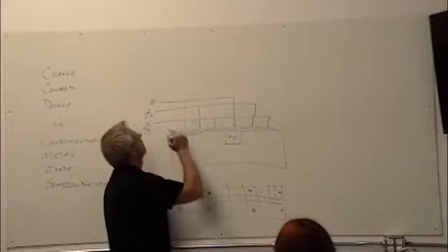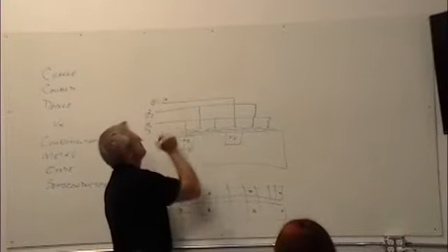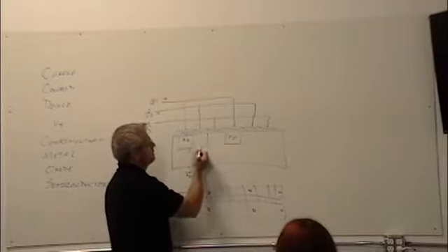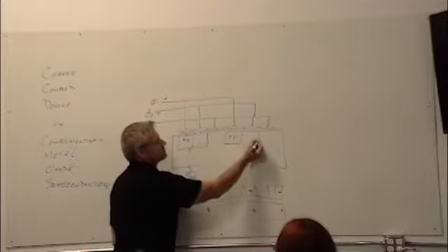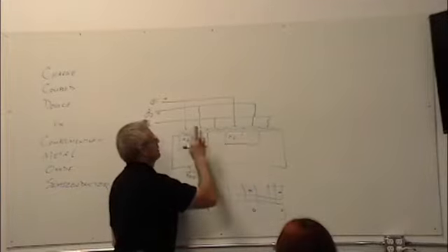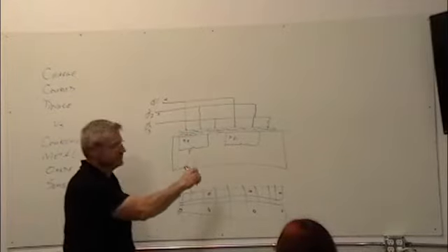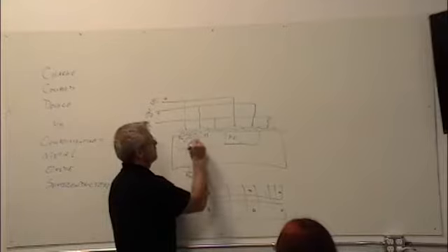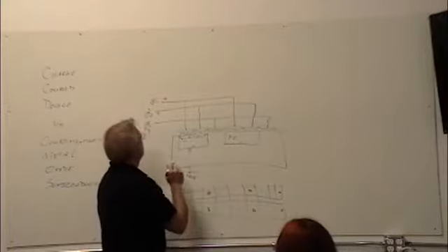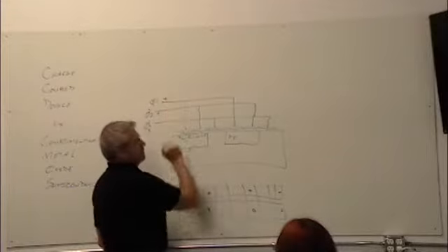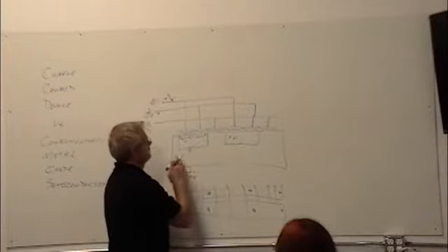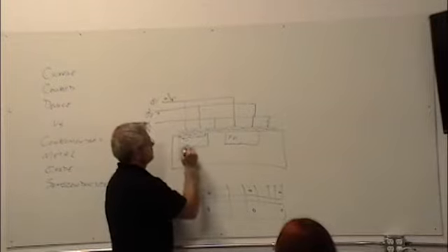Now I say, hey, you know what? This one's plus. I'm going to put charge on that one. And now this well is going to look kind of like that, and this one's going to look kind of like that, because now I've got the electric field on both of them. And now my electron pile that was here kind of spills over. And now I relatively slowly take that down to a negative voltage. And this well slowly comes up and pushes those electrons over here.